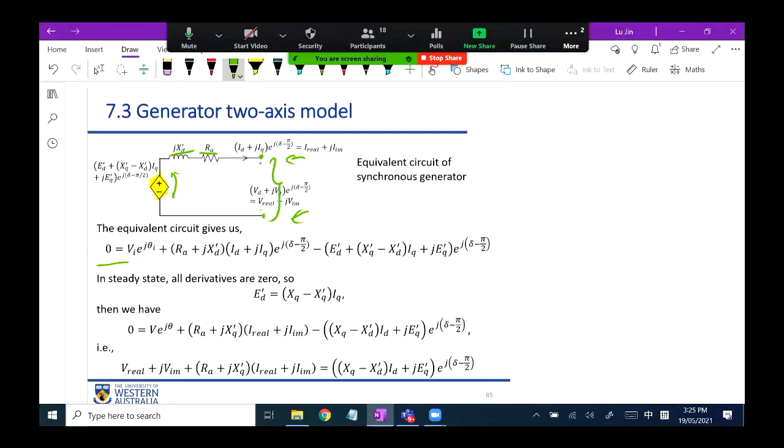What you are doing next here is a really, really long equation, right? Super easy. This is a KVL. So let's just clean this part up and you can see what happened. Besides, we are using a KVL for this loop. The first term is about the voltage across the terminal voltage. So this voltage here is given here, first term.